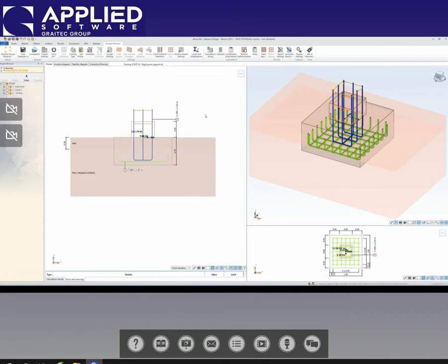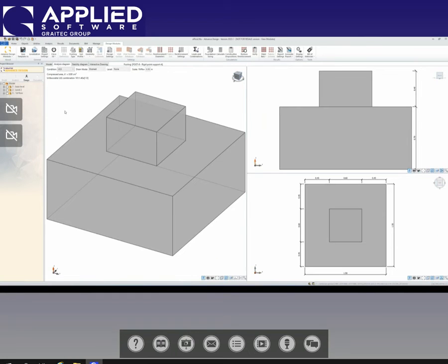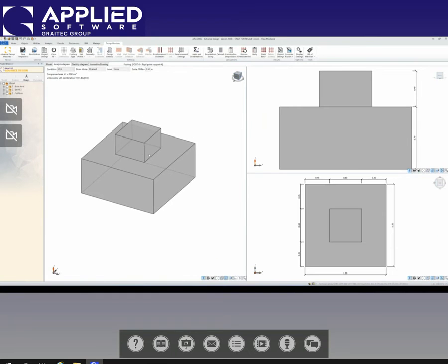It's going to calculate all of the required rebars inside the foundation. If there are some errors, in this case I see I have an error for SLS condition for the settlement. So it will also let us know if there are some errors in the design. Also here I can see the analysis diagram. For Advanced Design, we can check the stability diagram.